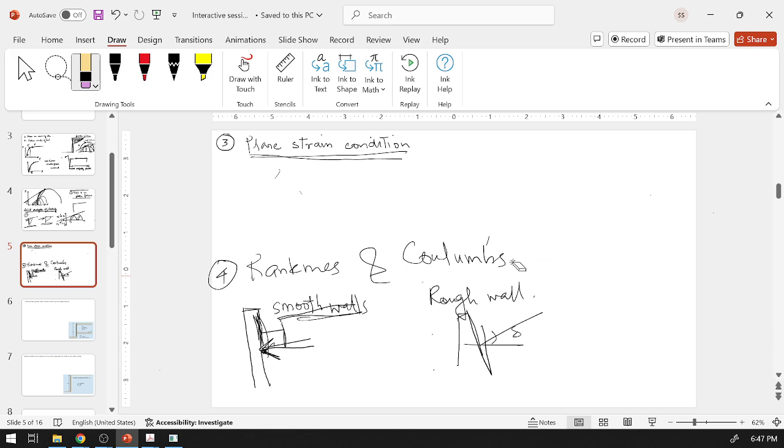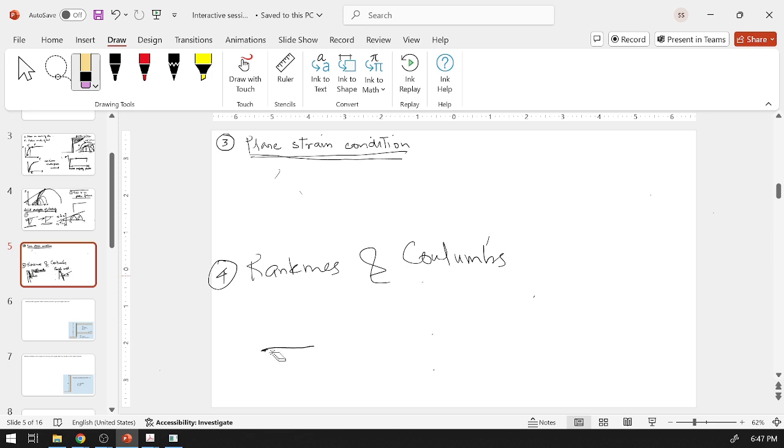I know we start studying about horizontal wall, vertical wall, inclined backfill, inclined back of soil, and out of all these conditions, we forget the basic thing. The basic thing is that this is a rough back, and thus the resultant will have an inclination to the wall, while in Rankine's theory we have a smooth wall and it will not have an inclination.